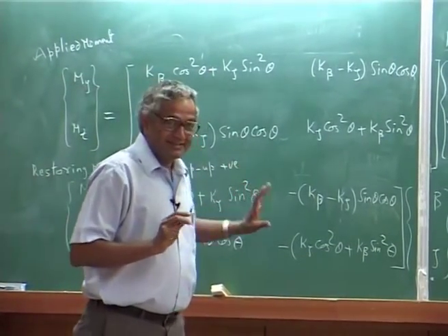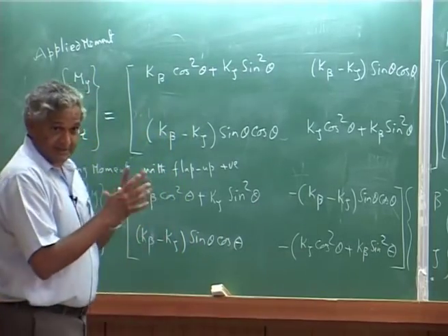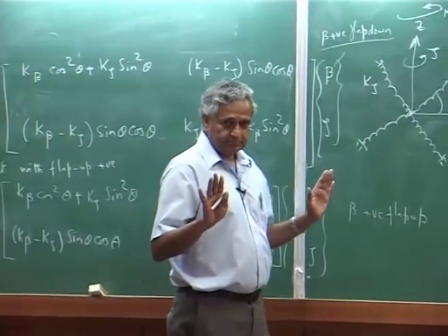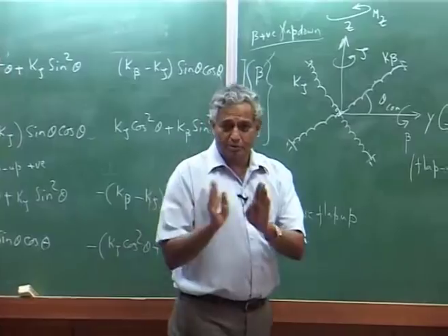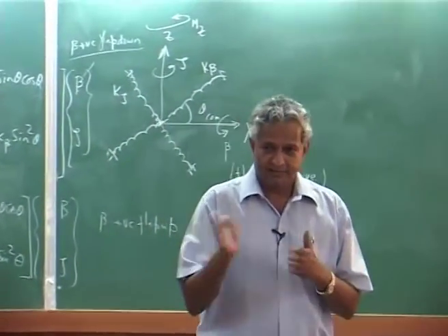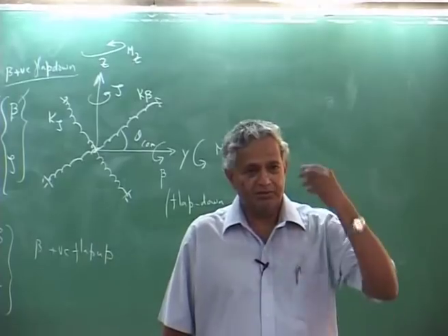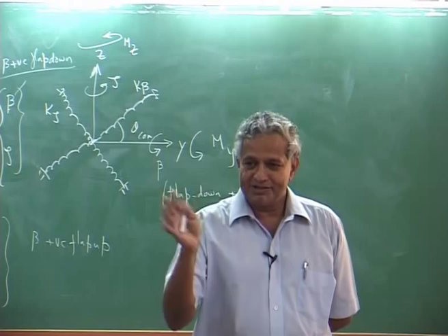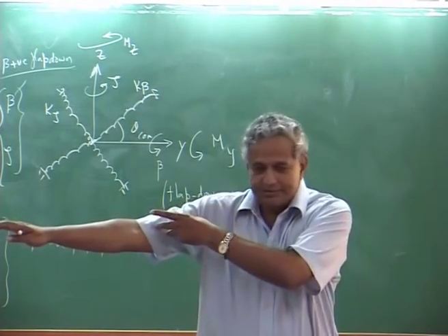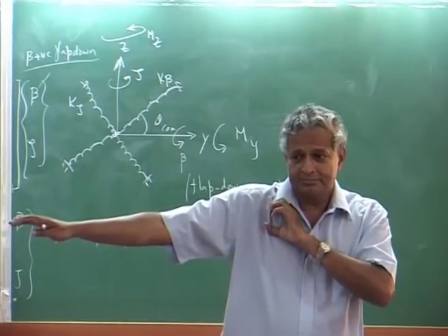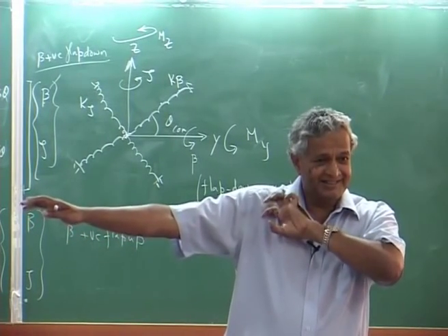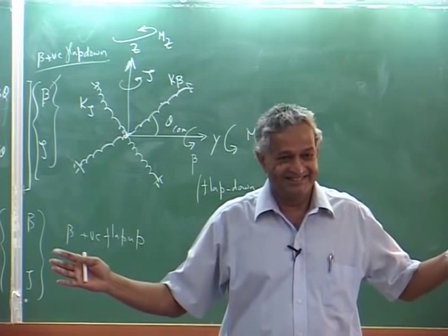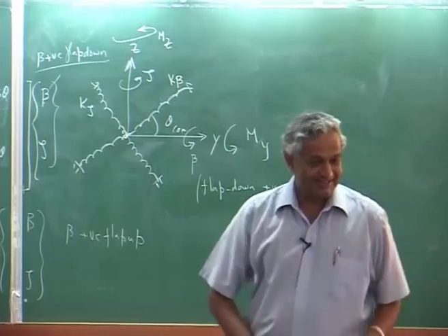But what I want to discuss here is, this is very interesting discussion. If I introduce pitch bearing inboard of flap and lag hinges, I introduce flap lag coupling, and all the hingeless blades, because in a hingeless blade the pitch bearing is inboard, you change the pitch here, coupling is always there, you can't avoid. Now, how much coupling comes? This is again, see, lot of debate.